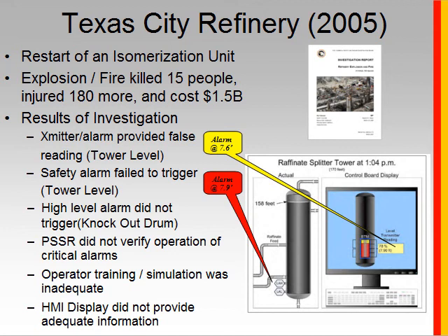We talked about how there was a misleading level measurement in the tank. Well, you might expect that on a well-designed display, there would be other information as to what was going on in the process that might trigger the operator to think that something is going on differently than what that level measurement shows, or that there might be something wrong with that level measurement. If you're seeing a flow coming into the tank, a greater than zero flow rate coming in, and your level is going down, then you potentially know that something is not working correctly.